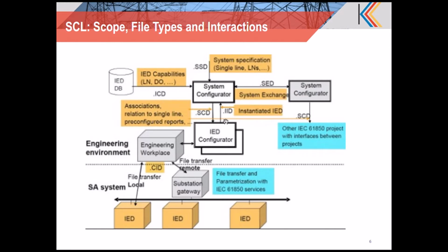That is, the vendor IED configuration tool will be provided with an SCD file, and the vendor IED tool will be used to configure the corresponding vendor IEDs. This SCD file is converted into a Configured IED Description, a CID file, which can be downloaded onto multiple IEDs in the system.